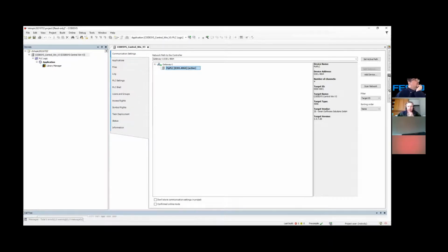Okay, thank you. Right, guys, check here. The moment when I click on my gateway and I click on the scan, that's the way you will also connect to a real PLC by clicking on the scan. If you have set up your interface, it will pick it up automatically. Okay, there it is now. That's the hardware that I've actually picked up, for example.